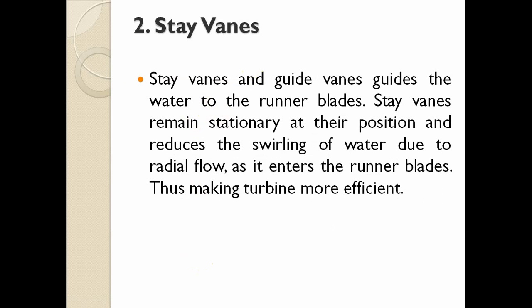Next one, stay vanes. The second part of the turbine is stay vanes. Stay vanes and guide vanes guide the water to the runner blades. Stay vanes remain stationary at their position and reduce the swirling of water due to radial flow as it enters the runner blades, thus making the turbine more efficient.